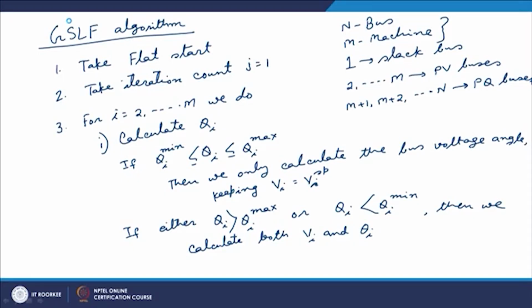And then, third, for i equal to m plus 1 to n, that is for load buses, we calculate both Vi and theta i.